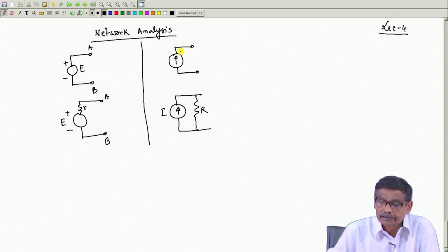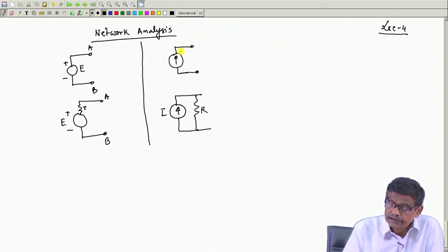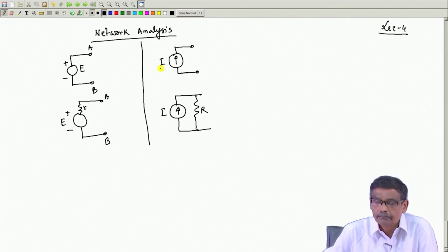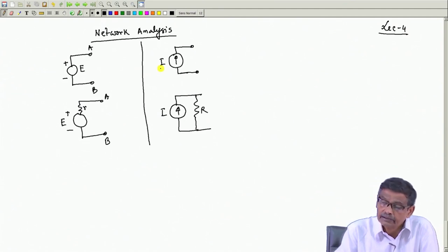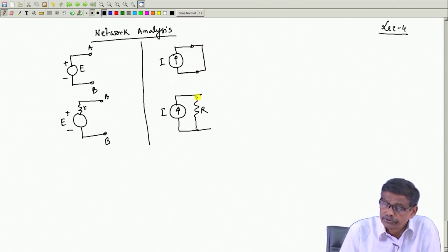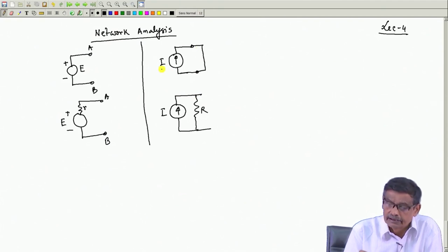So, it is open circuited, since the current source will try to drive current in whichever branch you connect in the circuit, irrespective of what impedance you have connected. Therefore, when open circuited, the impedance is very large and a large voltage may appear. Therefore, an ideal or practical current source should be kept open circuited like this.